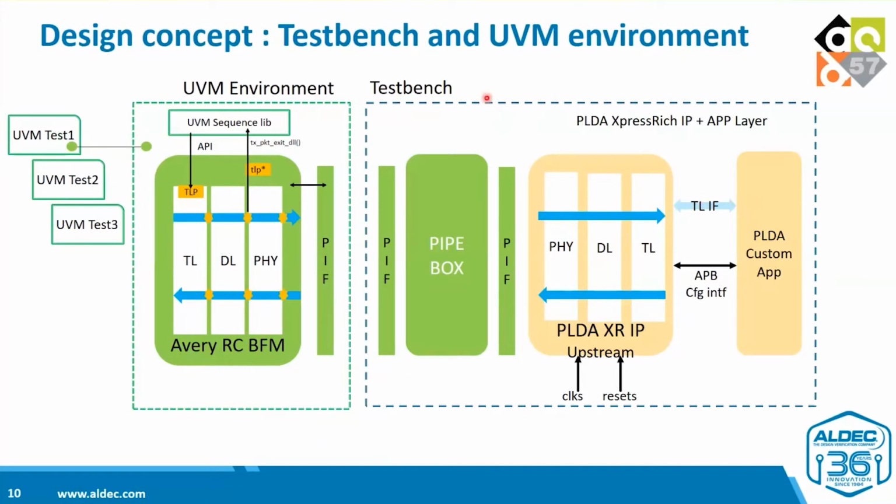And so in the test bench, this is essentially a Verilog module. The PLDA pipe interface is then connected to a pipe box from Avery. This is just a pipe-to-pipe connector. And so this supports different modes of the pipe spec. You know, there's pipe 4.2 and 5.1. It also supports the low pin count and SerDes architecture. And so PLDA connects on one side to this pipe box. This is the upstream port.